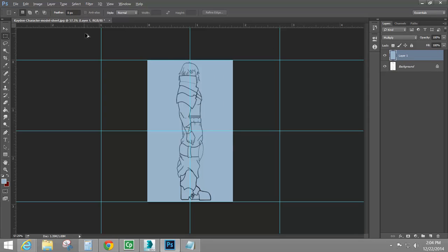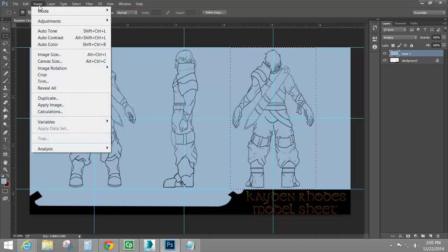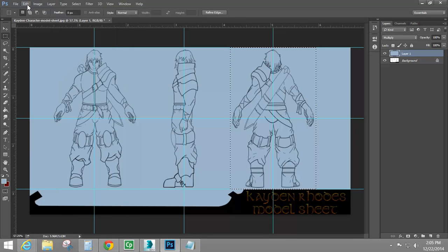Okay. Now I'm going to undo back to here, and I'm going to take this again, hold Shift, drag it over, and it's going to snap around this character as well. It's going to snap to the middle. The reason I started with the window selection on this character is because I know from the side view they're going to be more narrow. And the other thing is, I know I had a lot of dead space around the edge of that image, but I did that so all of my images are exactly the same size, so that makes it a lot easier for me.